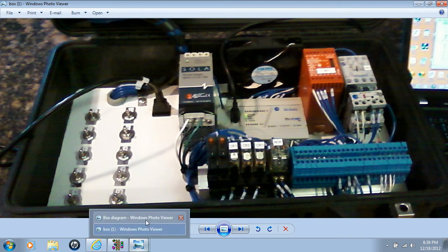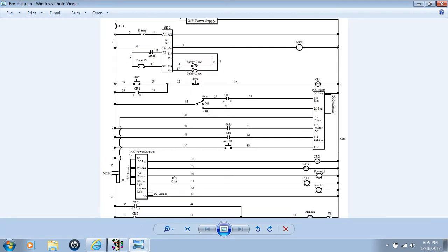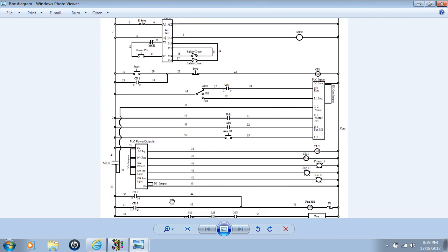And on the electrical diagram, what that looks like is this. You have output 1 coming on, turning on CR3, and when CR3 energizes, you'll see here's a CR3 contact right here. That's going to close, that's going to fire this MS. All these MS contacts are then going to close. And you'll see here's an MS contact here going to the PLC input 4.